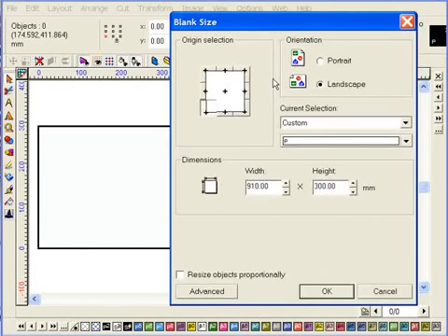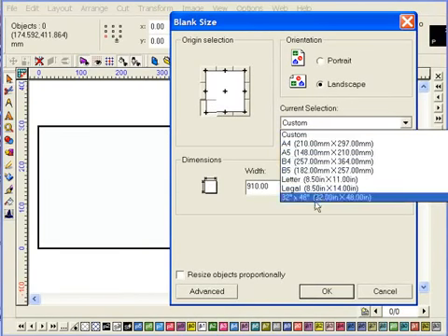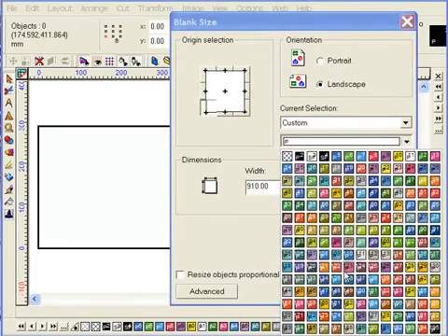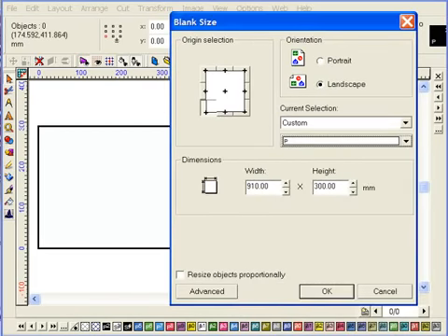The main parameters you will regularly change here are the dimensions of the sign blank and possibly the page orientation. You can also add a colour to the sign blank from this palette, but this will only show up if you have the Show Substrate option disabled in the View menu. Another way to add a colour layer to the sign blank is by clicking Sign Blank Object. This will create a shape that has the same dimensions and coordinates as the sign blank. The newly created shape will be placed at the bottom layer order so that it will appear under other workspace shapes. It can then be coloured to your choice by picking a colour from the main colour palette in the SignLab workspace.